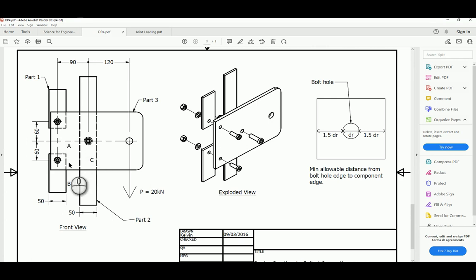Right, we have some constraints that we need to work with. For example, we could say it's bolted onto thin strips. So we have a guidance as to how big the bolt should be or should not be. If we cross a certain diameter bolt, we could actually tear the strips itself. Right, so we will see how we're going to factor in all these things into this design practice and also into the sizing of these 3 bolts.